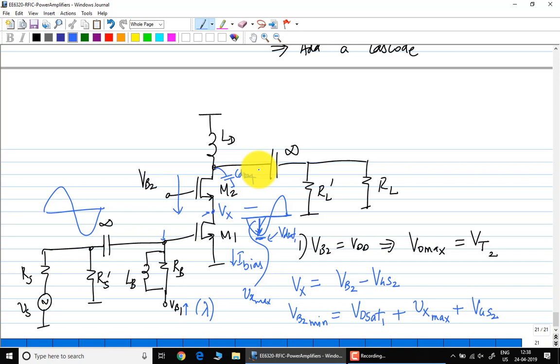And second thing is, remember that M1 is already like 1 millimeter. You are now talking about making the cascode 3-4 millimeters. This is not going to be tenable eventually, purely because of area and capacitance concerns. Any other questions?